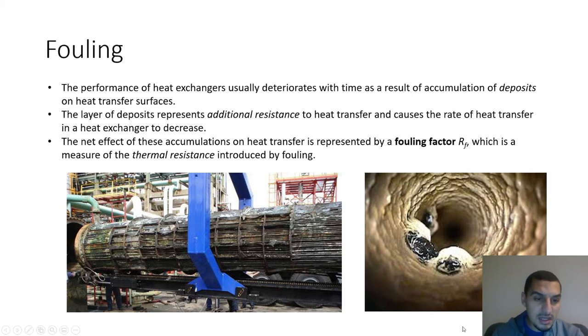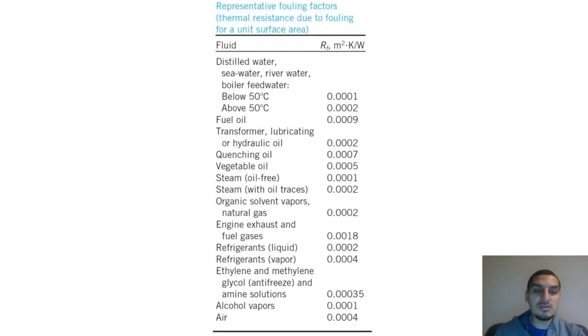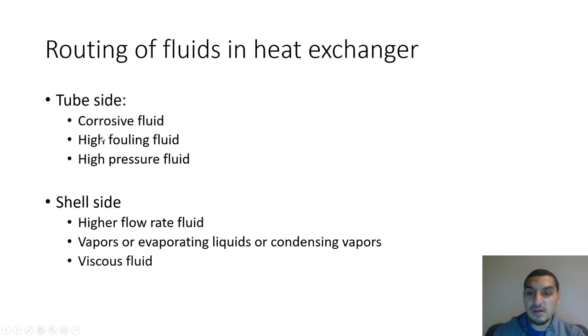Inside the tube, in a case like this, there are some tools like a drilling machine and stuff like that that has a brush and can clean this fouling inside. But in case of between the tubes, it's not easy, if it's possible, because in some cases it's not even possible to do that. So it's better to route the high fouling fluid in the tubes.